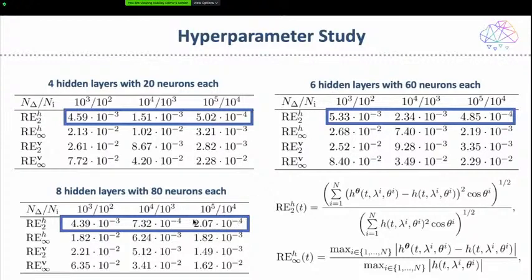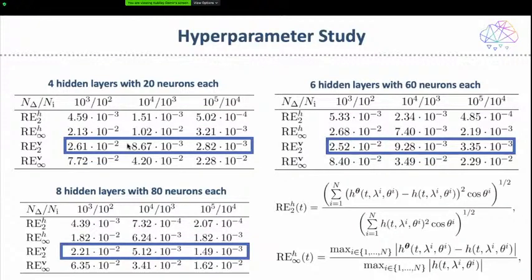But the more essential factor is definitely the number of collocation points, which means maybe if you don't use enough, it might be overfitting. And it's necessary to take a high number of points. However, they don't use all of these points at every single training step, but this is the full batch, and they always use a mini batch with 1,000 points in the domain and 100 for the initial conditions. Basically the same as I said before also applies to the velocity fields. Again, you see that it makes a bigger difference to increase the number of collocation points than to have a bigger network.